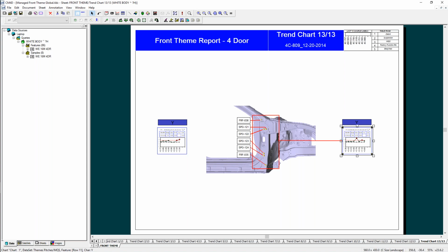Now, the measured data that you've collected can be mined even further to reveal how your parts could fit together before their actual assembly. This can be done by creating what are known as virtual alignments for your parts so that they share a common datum scheme.